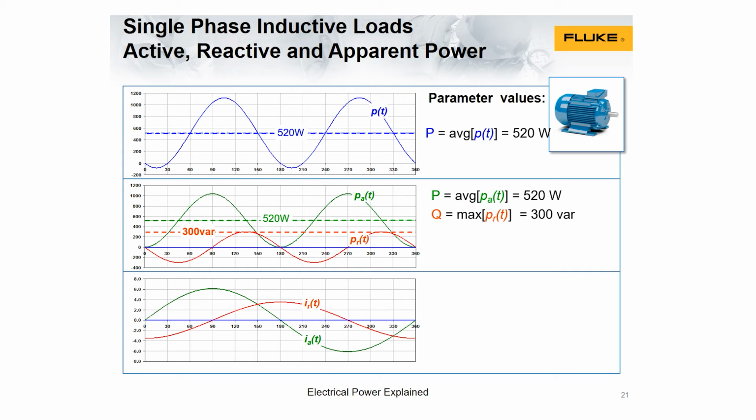Apparent power: seen from the utility side, URMS and IRMS are the parameters that determine the size of the network. For this reason, the apparent power S of 600 VA, the simple product of 120 volt URMS and 5 amp IRMS, is used as a measure for the power in the network. The active power is then URMS times IRMS times cosine phi.